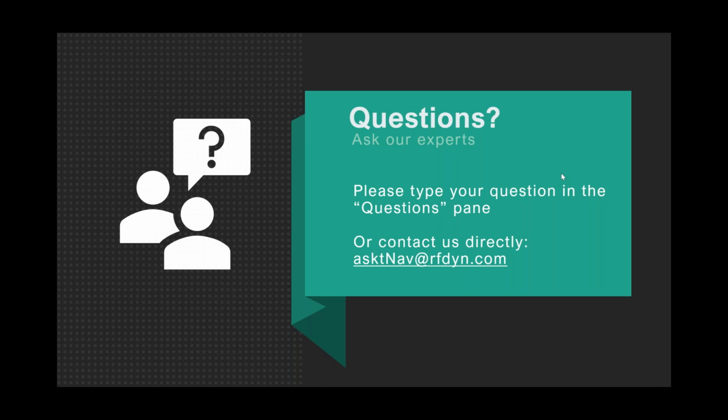Hello everyone, this is Nestor from Calgary. So there's one question here that says, can production data be loaded without dates? For example, as time from start of test. Yeah, the answer for that is yes. You'll need to set the start date first and the time, and then the dates could be calculated based on elapsed time.